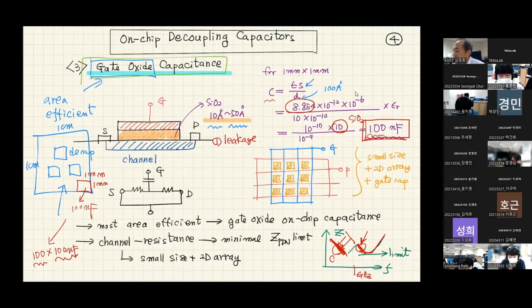Sometimes if you are breaking this dielectric, electrons will leak. So potentially it's going to have a leakage problem if your very thin dielectric is not a perfect material. You're going to have some risk of leakage.